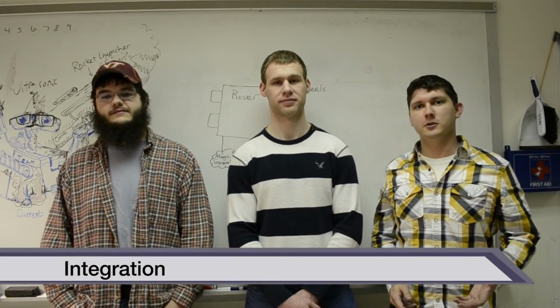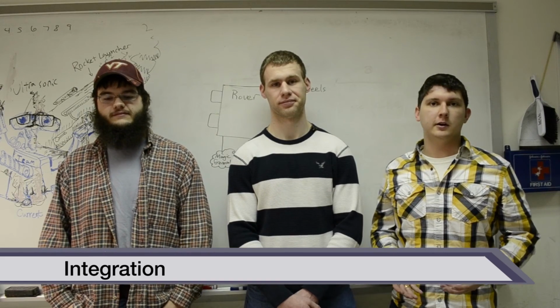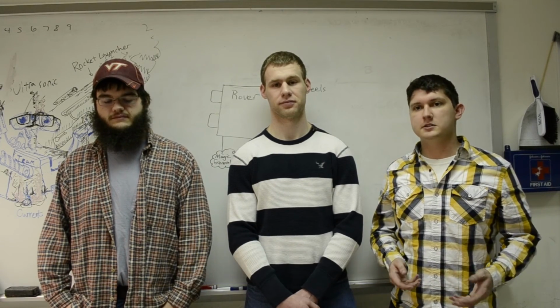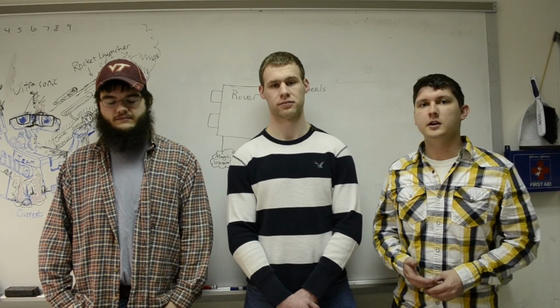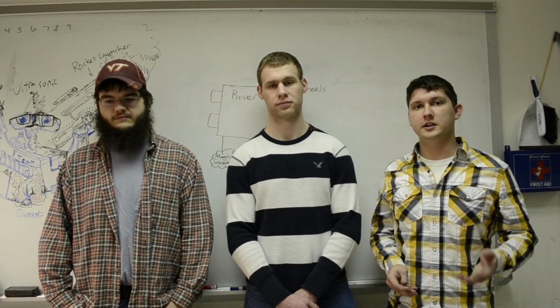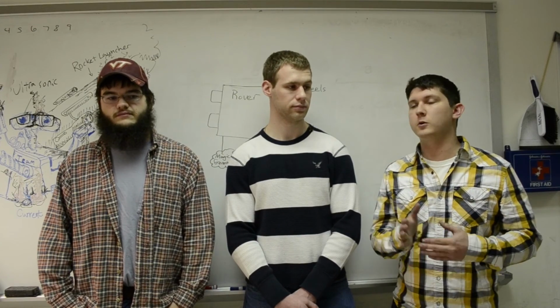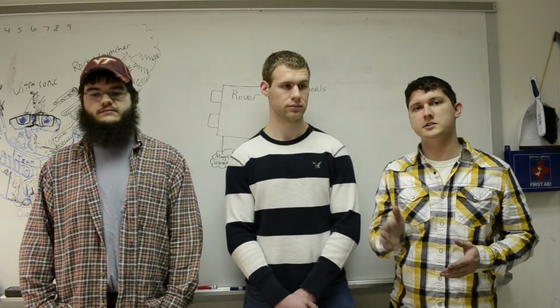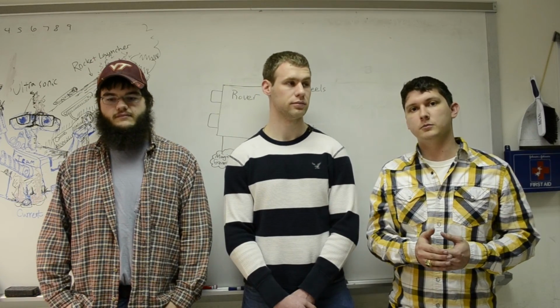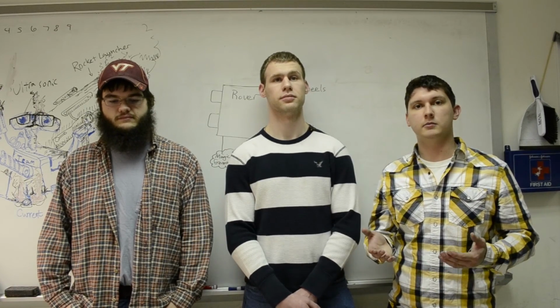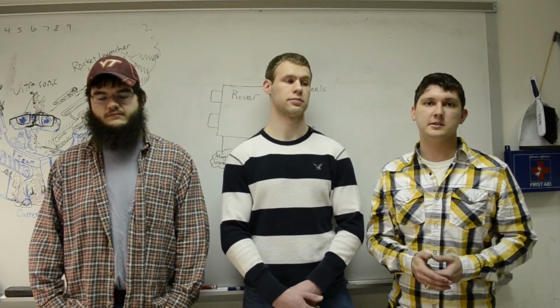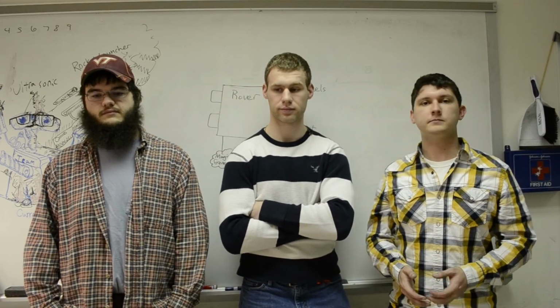So for the integration of the rover, everything went fairly well, although we did have to make a lot of minor tweaks between the algorithm and the rover itself to get everything to work together well. For instance, for the algorithms, initially they used very small movements forward and backwards and very small rotations in either direction, which caused some twitching motions over the rover to sort of stall out or slip in a lot of cases. So we used larger rotations and larger movements to get over that issue.